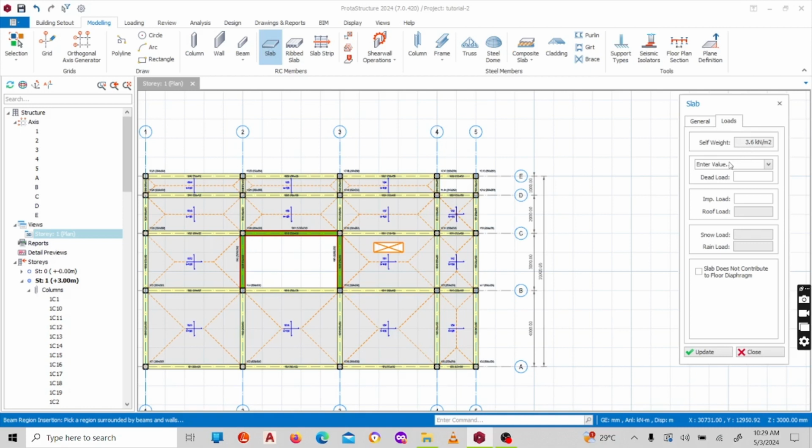And for the dead load here, I can name it. Be it maybe a flat roof, a room, a terrace, a balcony, or a large slab. And then I can place the load here. Say it is 1 kilonewton or 2 kilonewton. I can press it there. And for the imposed load, this is being fed according to the code that we've been using.